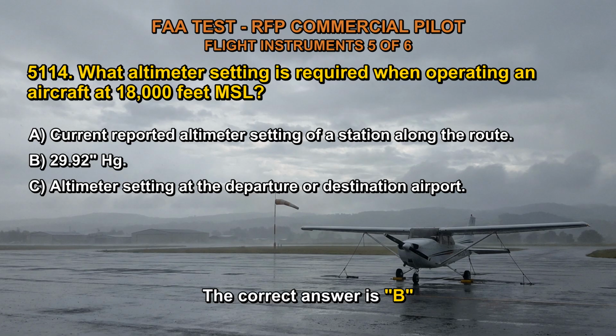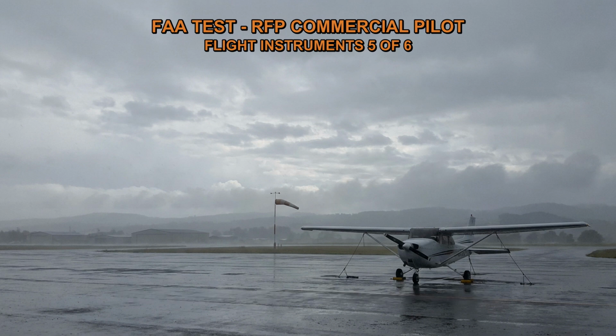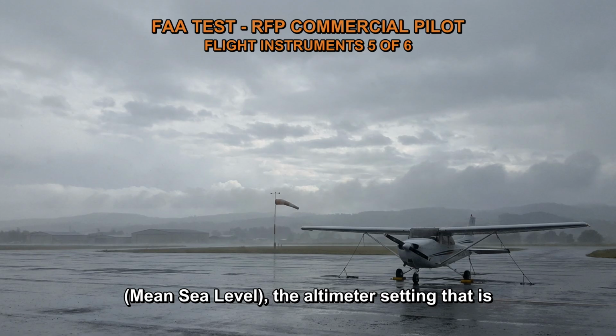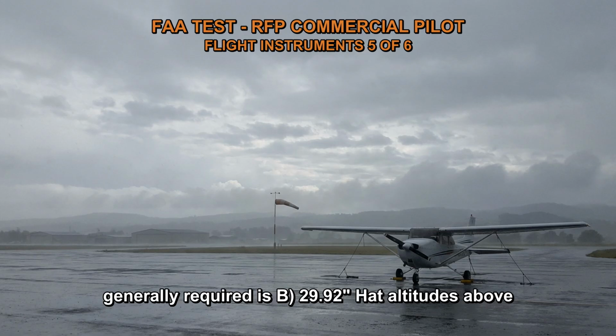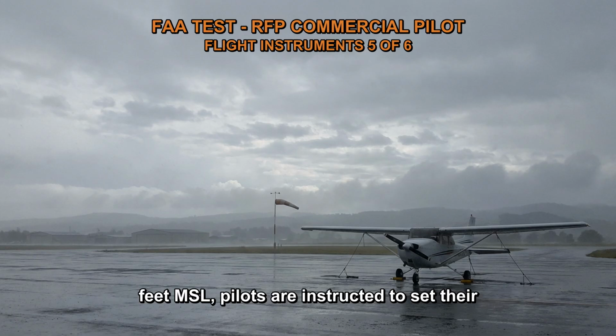The correct answer is B. When operating an aircraft at 18,000 feet MSL, mean sea level, the altimeter setting that is generally required is B, 29.92 inch at altitudes above the transition level, which is typically around 18,000 feet MSL.